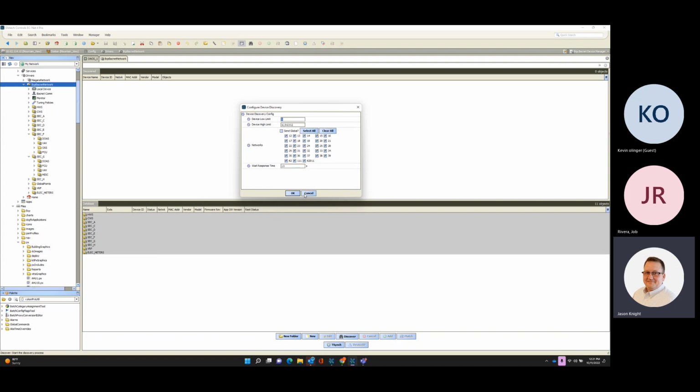The IT department wanted each standalone device, each MAC address. The MAC is defining the network card in the main processor of each chiller and each boiler, right? They wanted those to have individual home runs pulled from that piece of equipment to an IDF room. So I was like, okay, well, how are we going to do that when I've got a chiller that's 700, 800 yards from the closest IDF room in D?